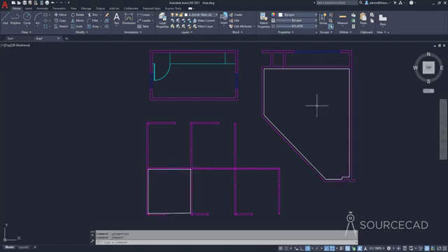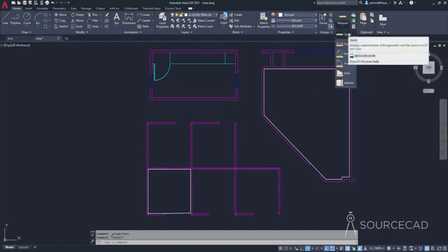So these are the different ways of finding area. I now prefer this quick tool because, as you can see, it's very quick, and you can find areas of several different regions quickly using this. And if you just want to find out areas of a closed region, all you've got to do is hide anything that is inside that closed region or that may end up causing errors in your areas of the closed region. You can just hide those objects and use the quick tool.